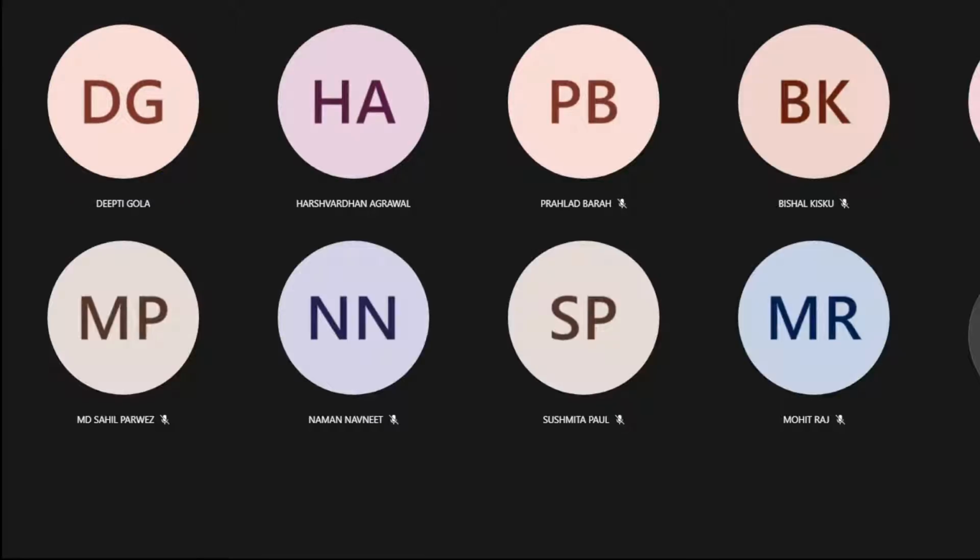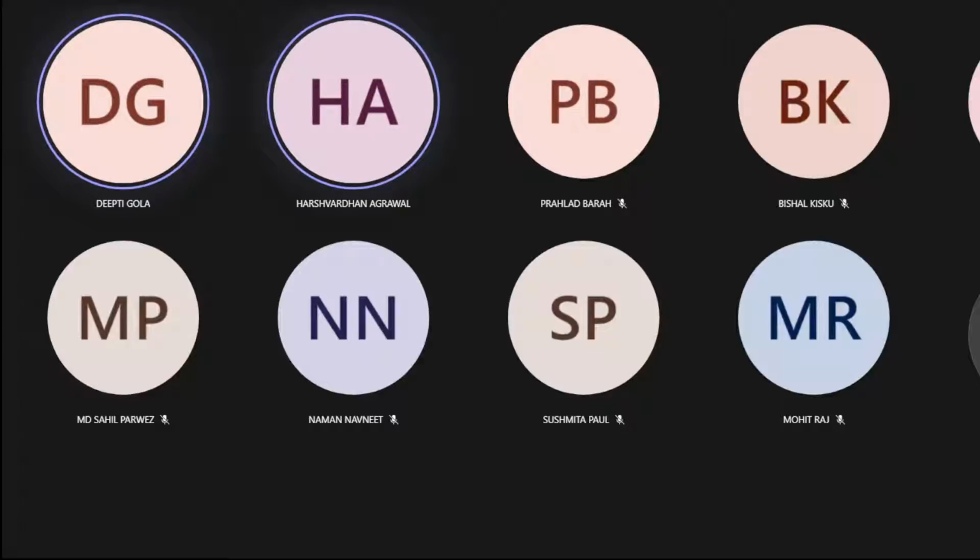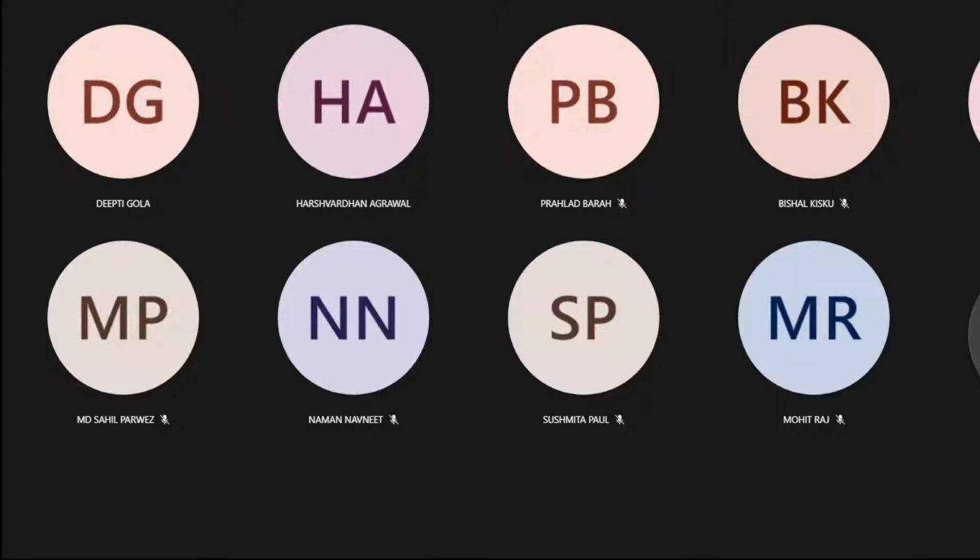And ma'am, RC1, RC2? RC1, RC2 should be 1 kilo ohm only. Okay, ma'am. And also do one thing, between this RC1 and capacitance C1, please just add one LED so that we can see if the LED is glowing, that means the current is flowing through it, right? It's the same C1.